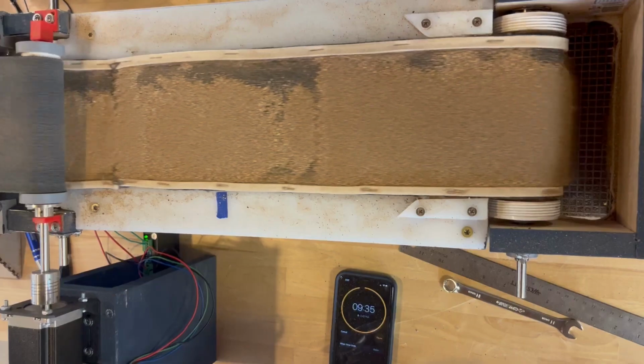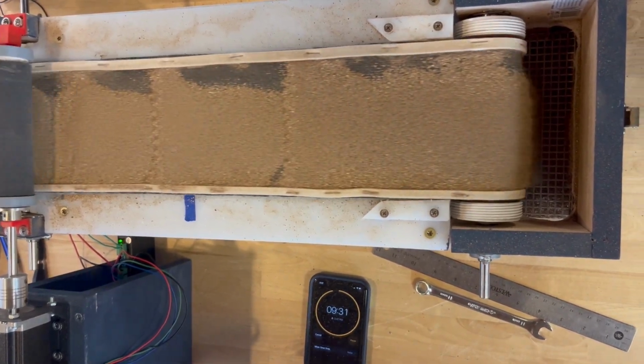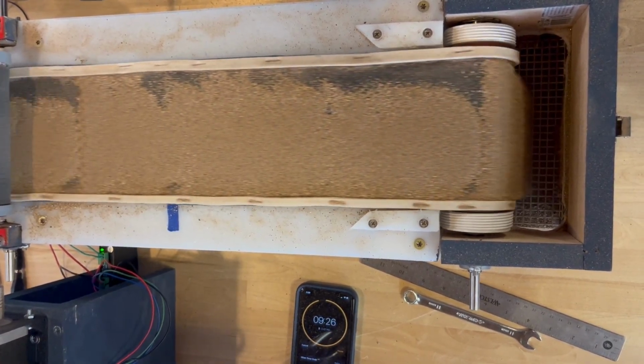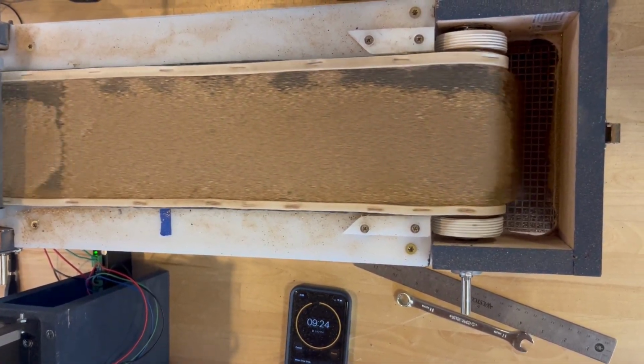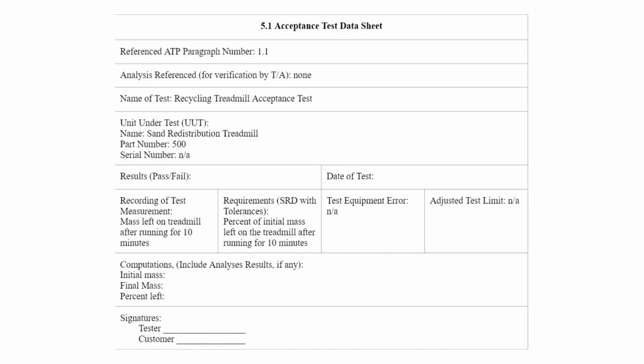The SRT subsystem was designed to collect the regolith at one end of the treadmill and carry the regolith back up to the treadmill via a separate treadmill subsystem. The SRT needed to be angled underneath the treadmill to allow room for a filter subsystem, but not angled enough to allow the regolith to roll backwards down the sloped conveyor belt. The SRT uses compression between the SRT belt and the treadmill belt to transfer the regolith between the belts.